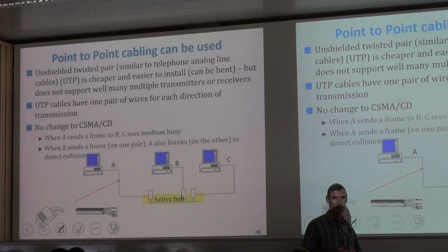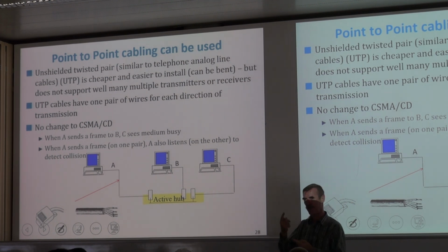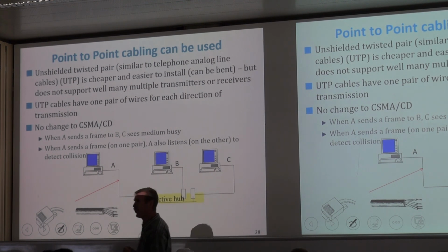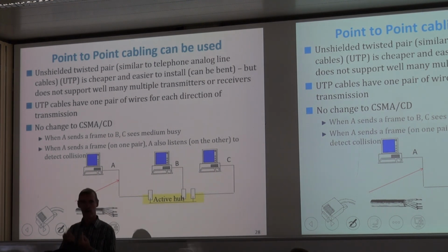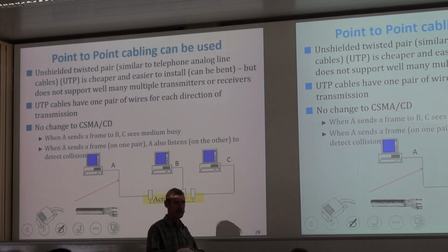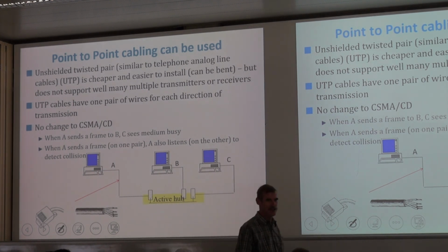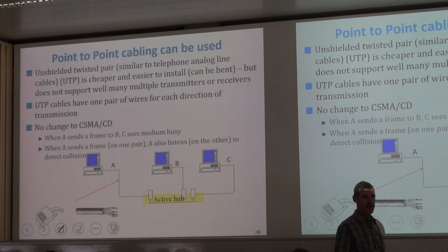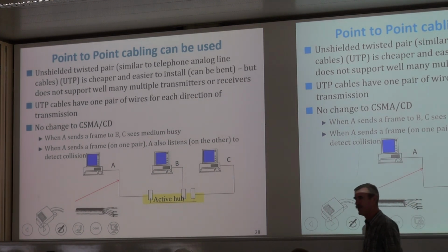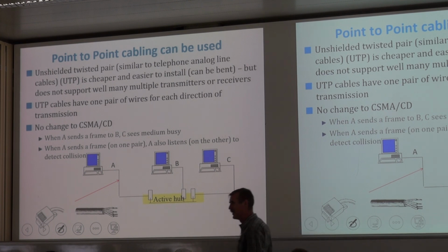reception of interference. So when you twist a cable, you make the two consecutive lobes have opposite orientation. So the electromagnetic waves that they emit are opposite. Since they're very close to each other, they almost cancel. That's for the emission side, so they emit less interference. And the laws of electromagnetism are completely symmetrical. Everything that works for sending works for receiving, so it's the same for receiving interference. So this is why you twist things.